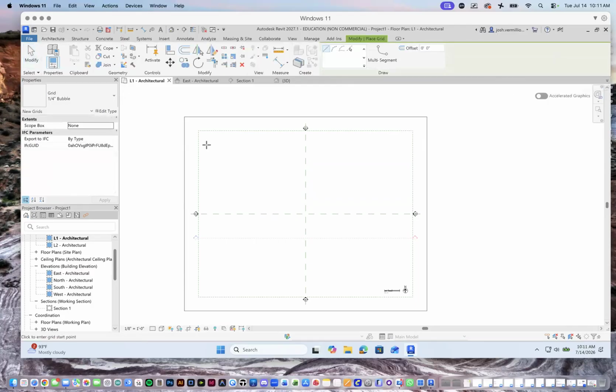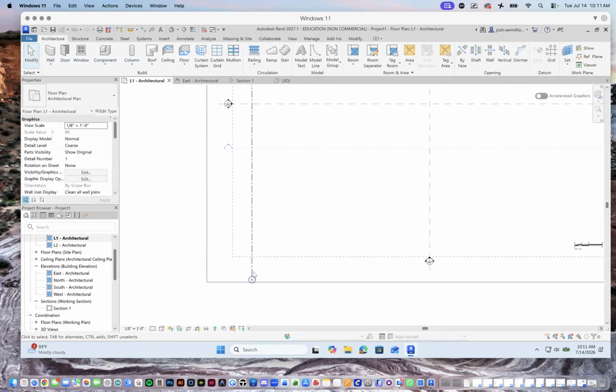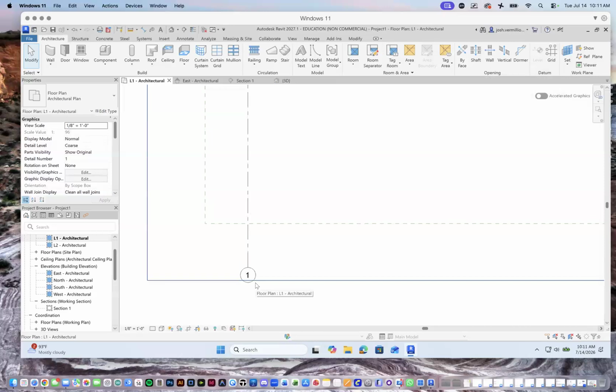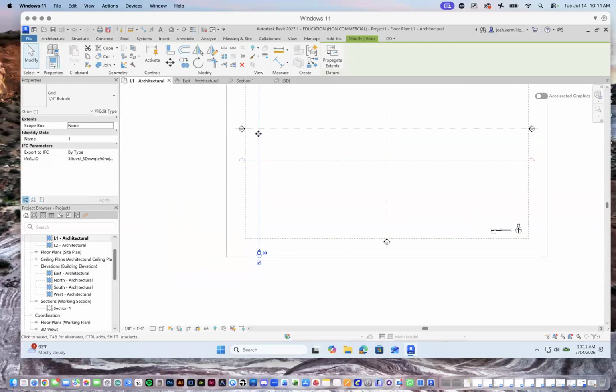So with grid, we can begin in top view and plan view. We can begin to draw a grid, right? And oftentimes this will correspond to a column grid, right? In other words, this will not just define and break up a large area into a smaller module cadence, but we'll also begin to talk about how things work structurally, right? Oftentimes, we'll put these grids in, and they correspond to the center lines where bearing walls, load bearing walls, or where columns are located, right?